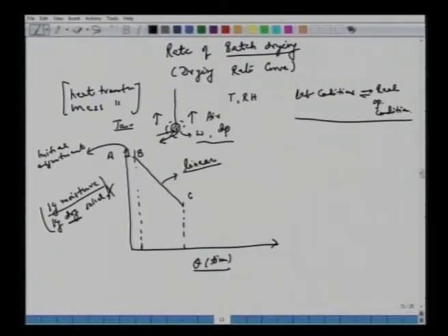Alright, so after the solid is warmed up or cooled and has reached the temperature, one monitors this very typical linear change in the weight loss. Then there is a slowdown. So let's see, we have till D here. Now we can say that there is a non-linear region. We will see this later: the linear curve represents the constant rate of drying, and the non-linear part, from C onward, we will call the falling rate. We'll come back to this later.